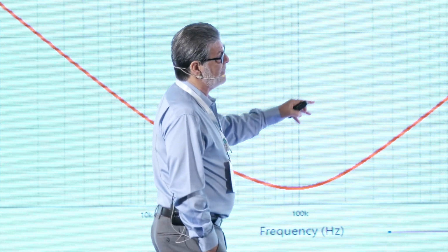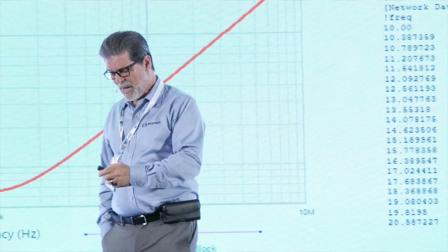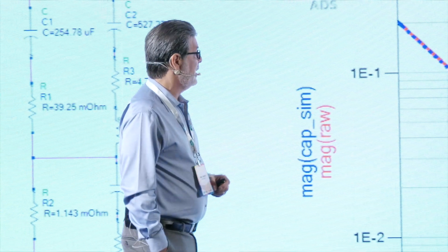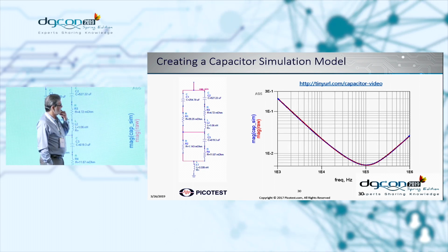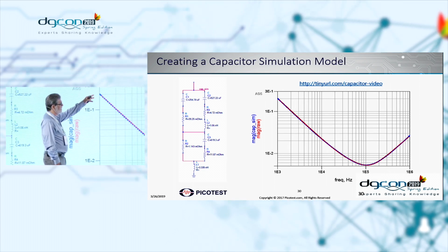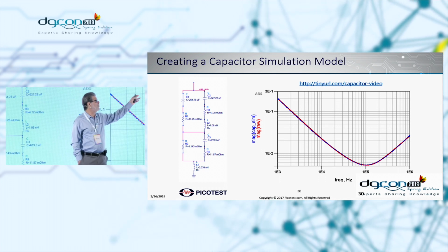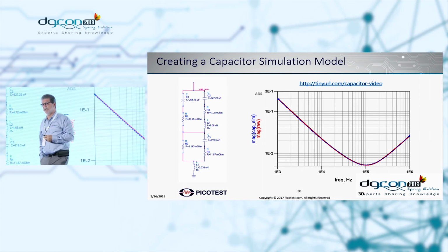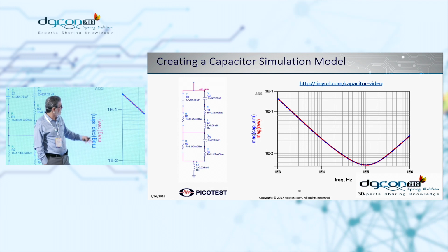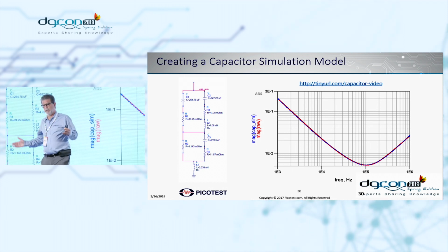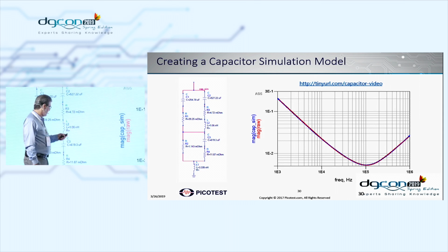We measure that using a vector network analyzer. We export that into S parameters, and then we can make broadband models of it for those that are using SPICE. I gave you a link there. There are actually 5 different videos under tinyurl.com/pi-videos. And one of those videos is how to make capacitor inductor models. But there's the measurement and the model overlaid. They're pretty close to perfect, and I can generally make that model in a few minutes.